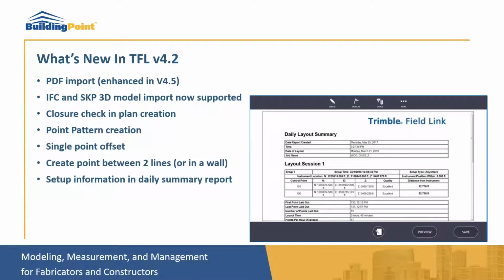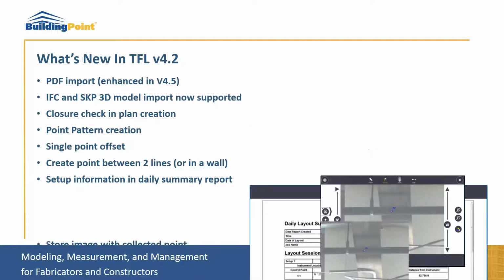Setup information has been made available in the daily summary report, so we now have that information on the instrument position and also the quality of our resection and the control points that are used available in the daily summary report for further use if we need to argue with anybody on our station or quality of our work. We have that information now made available.